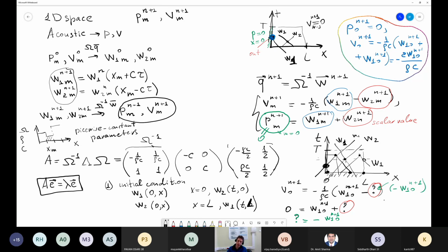This is trivial. If you want to obtain zero reflection in the 1D case, you have to pose that Q at the value n plus 1 at the next time layer at the position... you can use this approximation, dQ over dx at x equal to 0 is equal to 0. So this procedure is also quite trivial, so you will be able to incorporate it easily in your research code.